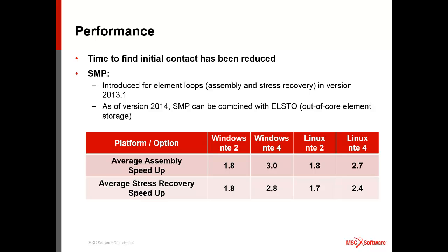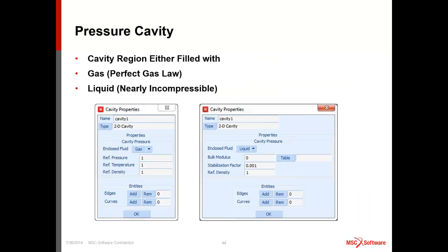The other improvement that has been done on performance is the Pardiso solver had some issues with out-of-core solution techniques. Some of those problems have been eliminated, but we also know that the Pardiso solver still is using more memory than our conventional default solver. But again, I strongly encourage people to use the Pardiso solver because it's much faster.